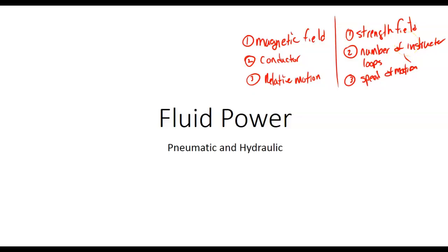What happens when you turn the solenoid off? That magnetic field comes collapsing back into that coil and produces a voltage that you just wouldn't realize. Now, the problem we have with solid state devices is they have what we call breakover voltages, which means if you exceed the breakover voltages on one of your output ports on your PLC, you're going to blow the output port out. So this